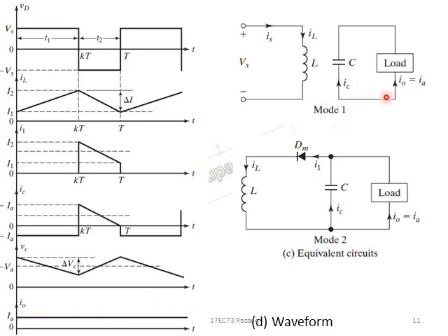So the load current is flowing in this direction and the capacitor current is shown like this, but the load current will freewheel like this. Hence it is opposite to the direction of IC shown, and so it will be negative I. This is the load current carried by the capacitor, from top to bottom. The arrow is shown in this direction, hence I show the capacitor current same as the load current but in the reverse direction. The capacitor voltage during this time will be falling, through the load.